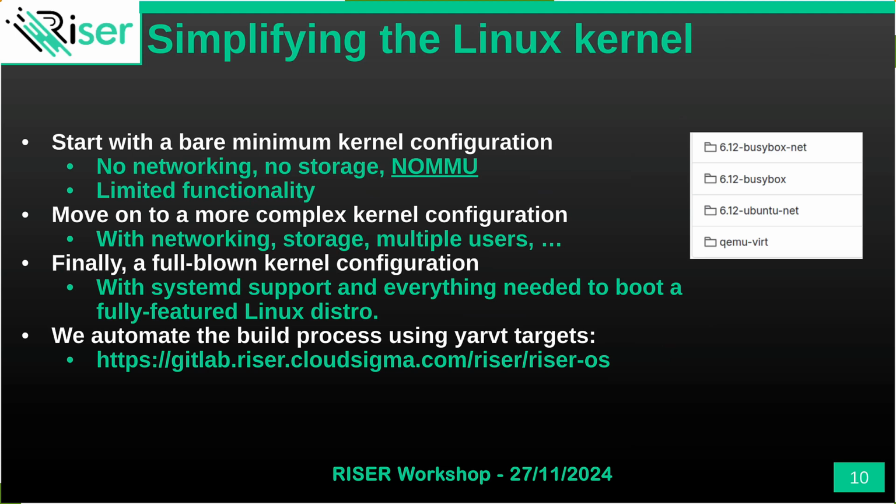You can do bare metal tests for testing the MMU. But when Linux boots and starts doing context switching and fences, and you start doing more complicated things, things break. So initially we start using Linux with the MMU disabled.